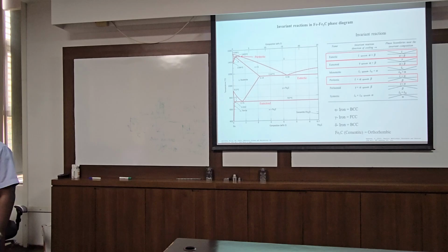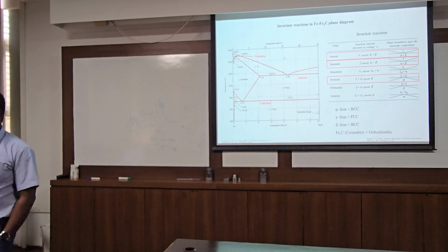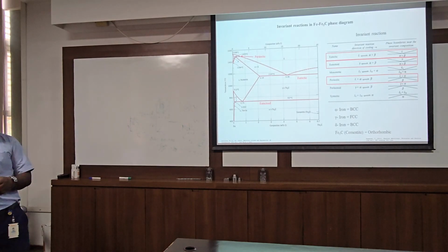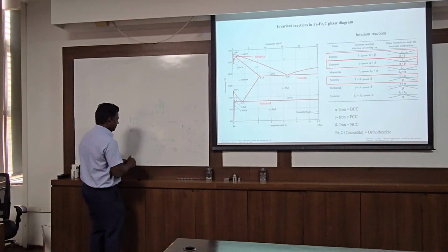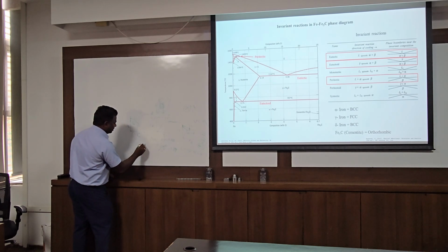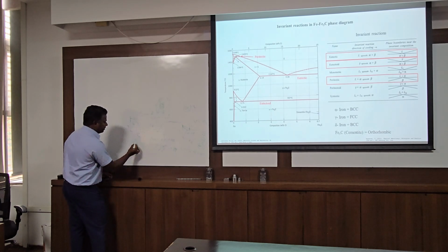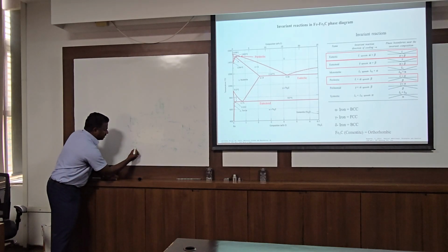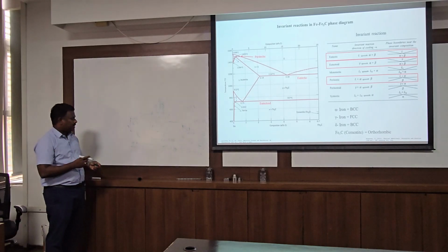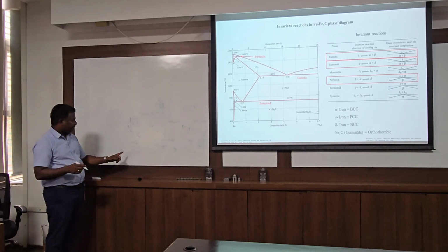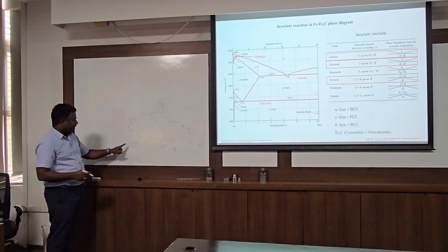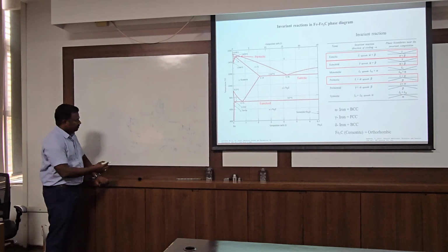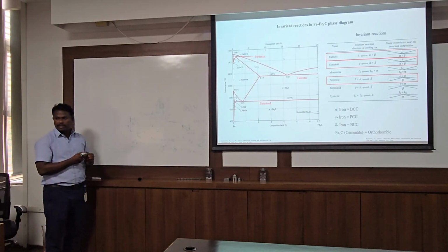Yes, that is correct. So basically what you said is correct. I will just explain elaborately. Atoms, suppose I have a set of atoms with an equivalent distance of a. What does it mean? Every atom has vibration around its mean position. What we take is the mean position. As we increase the temperature, the amplitude of vibration will change. So that is how the lattice parameter will increase as we increase the temperature.